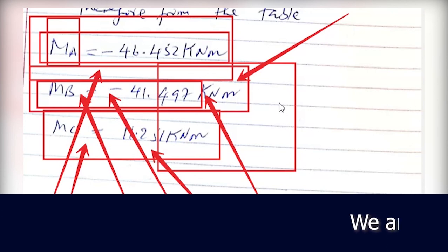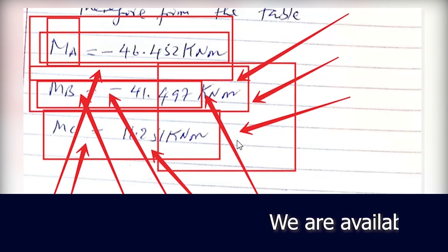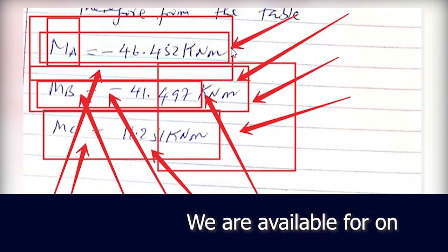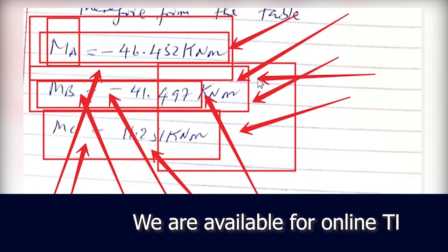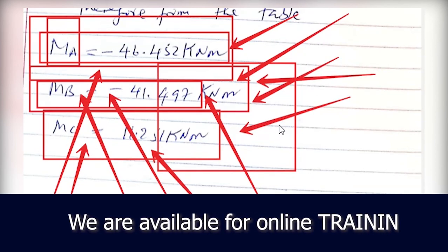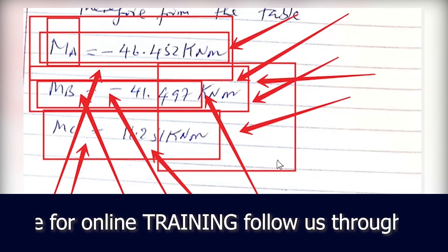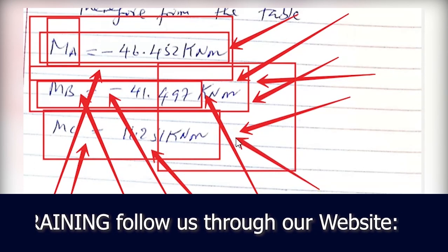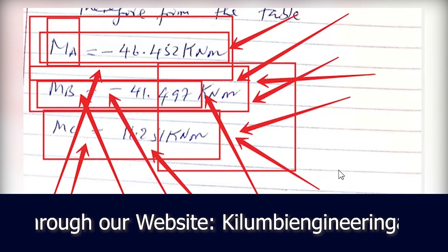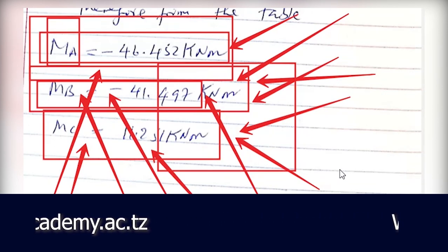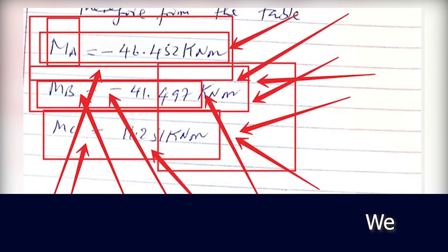So at equilibrium you can have two simultaneous equations which have the unknown values of reaction at B and C, or the unknown reactions between A and B. On substituting each into the other through the moment and the force equations, you can have your reactions, and hence you can have your shear force at the support, and you can draw your bending moment diagram.